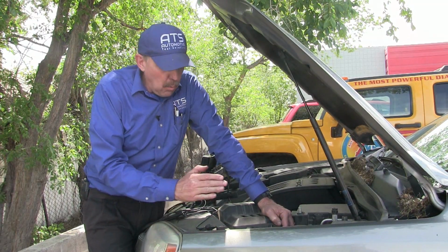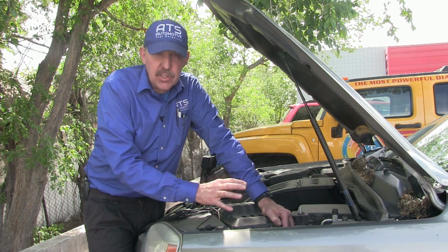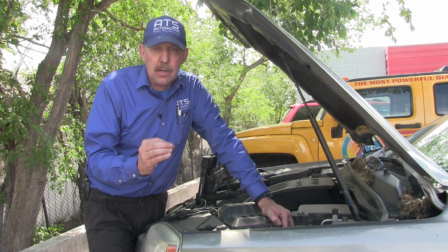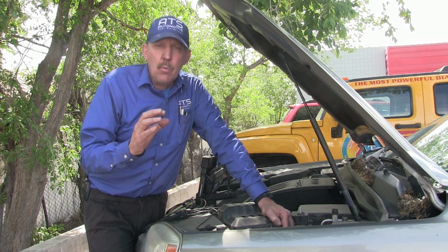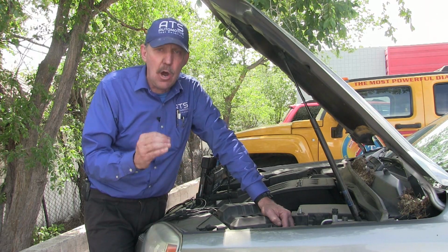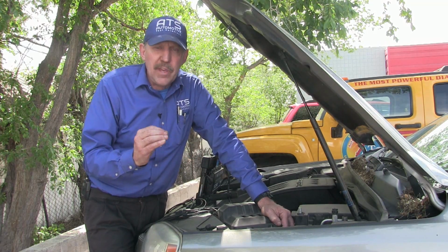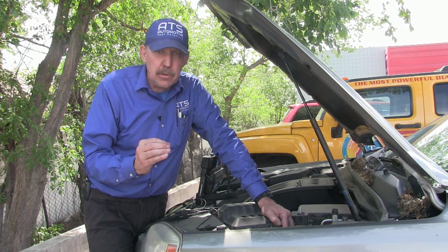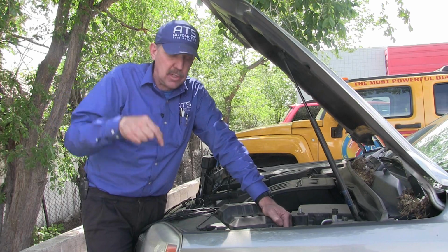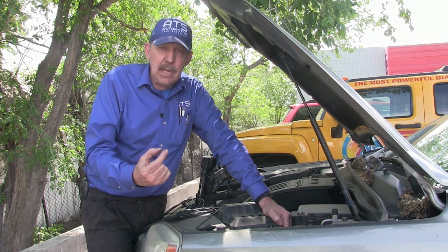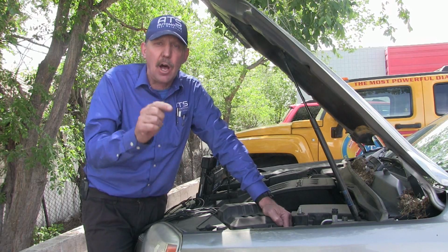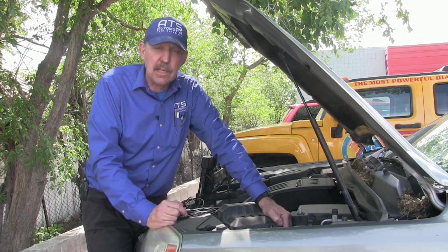So we don't want to take it apart. If you ever see this, don't take it apart to clean it now. We will need to take it apart and clean it once we're done with the car. Right now, I don't want to change anything. I don't want to disconnect anything until I know what I'm disconnecting. So the game I'm going to play is I'm going to take a screw and put a screw right down into the center of that battery post and connect to it. Now any voltage drop that I have between that connector and the post of the battery, I'll see that. So let's go ahead and get this connected.